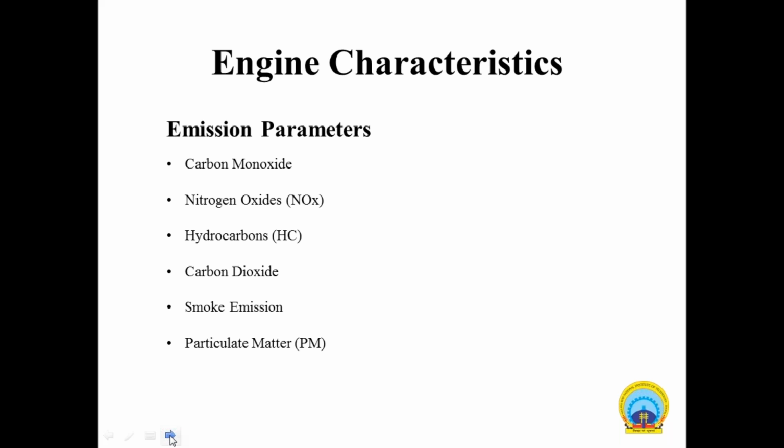Then NOx. In the exhaust of an IC engine, NOx refers to a class of compounds called nitrogen oxides. In diesel engine exhaust, nitric oxide is usually the most abundant nitrogen oxide and constitutes more than 70 to 90% of total NOx at engine-out conditions.